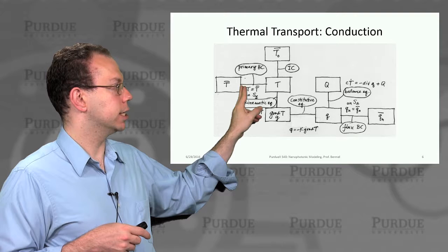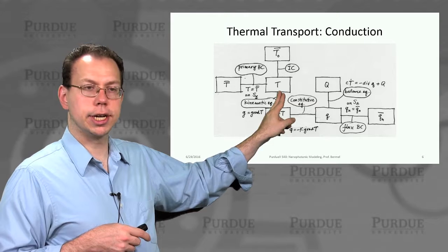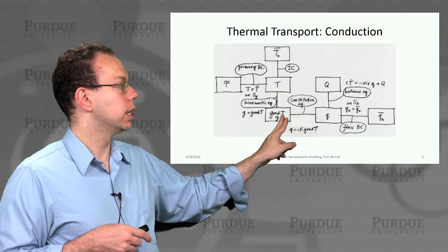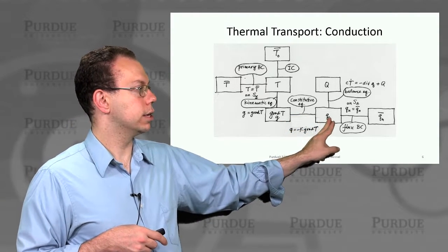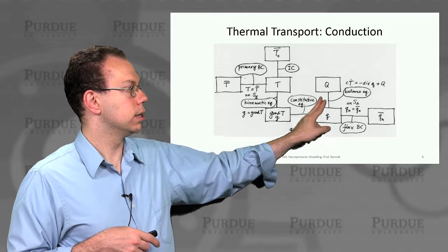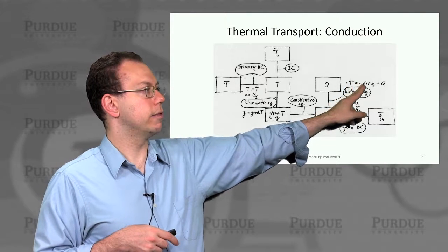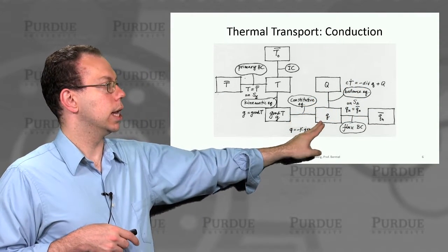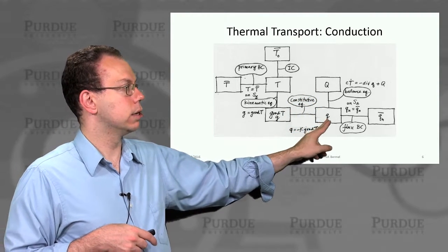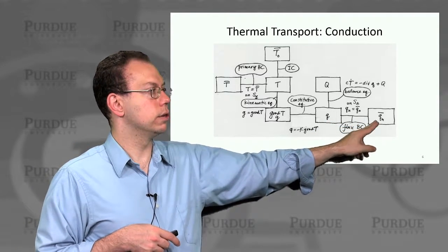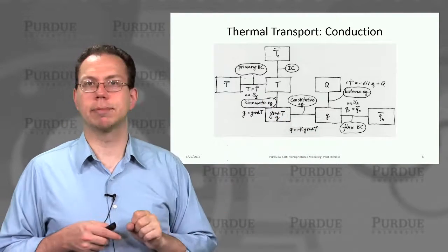And so what it's showing is basically you have temperatures creating either boundary conditions or initial conditions, depending on the type of problem you want to solve. And then you have the kinematic equation for the flow of heat, right? So this is Fourier's law that I talked about. And then you have this balance equation, which is C dT by dt equals minus divergence of Q plus capital Q. And so this is basically the net heat generation plus heat flow through the surface from Fourier's law, and then they're being combined through the flux boundary conditions into a solution for the temperature. And so you can all see everything connects back.